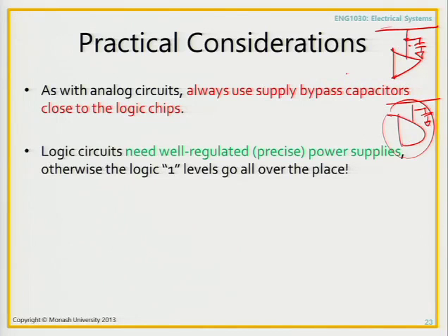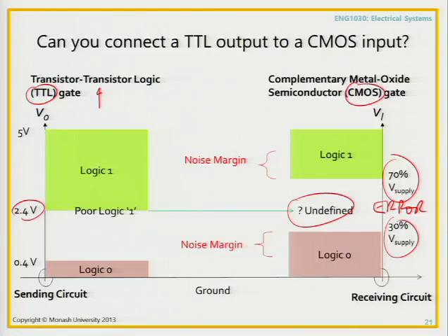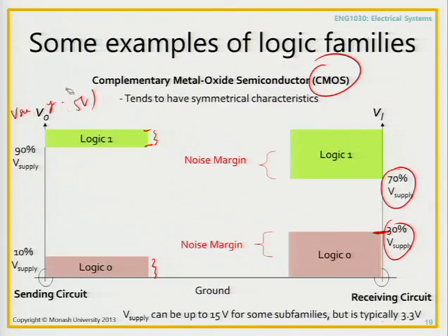Logic gates need really well-regulated power supplies, and that ties in with these supply bypass capacitors. This goes without saying, particularly with the CMOS example.